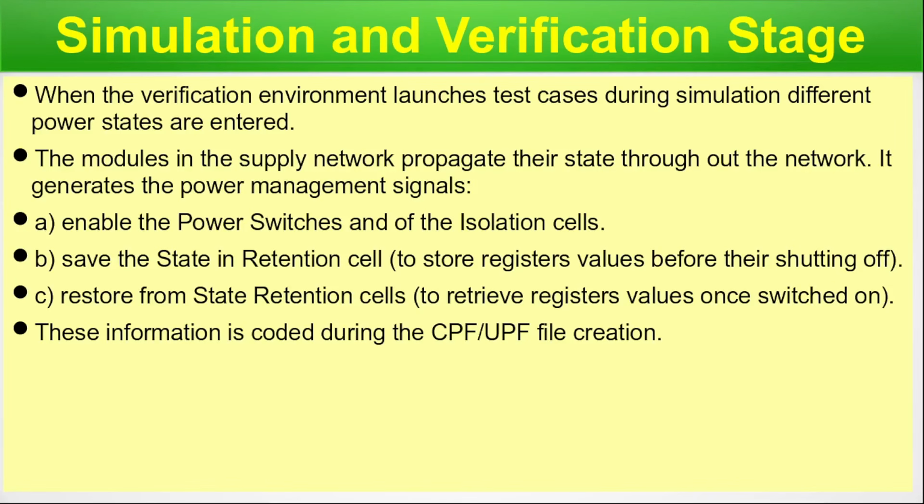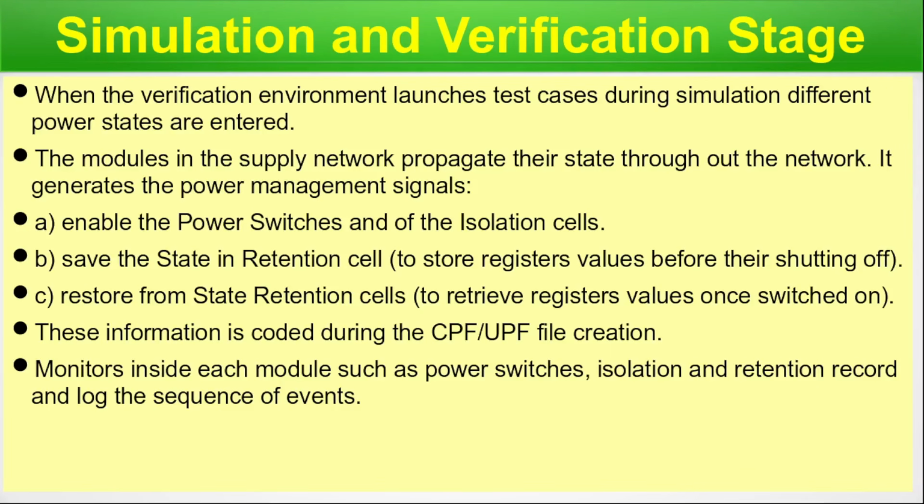This information is coded during the CPF or UPF file creation. Monitors inside each module, such as power switches, isolation and retention, record and log the sequence of events during the front-end simulation.